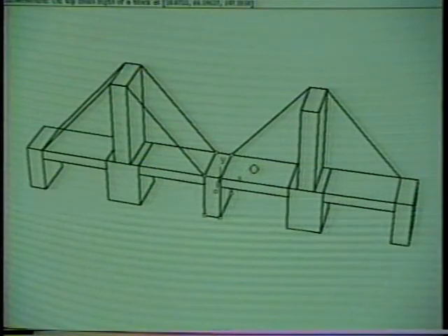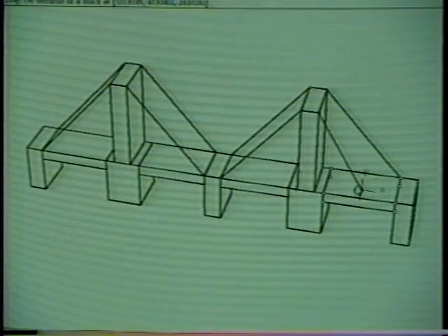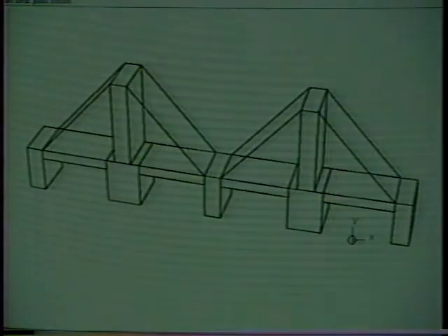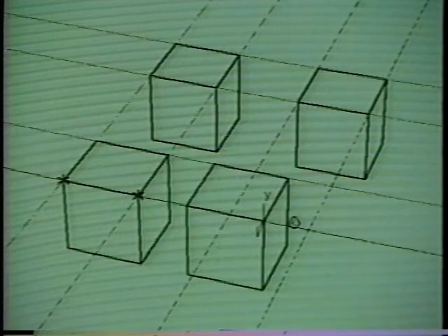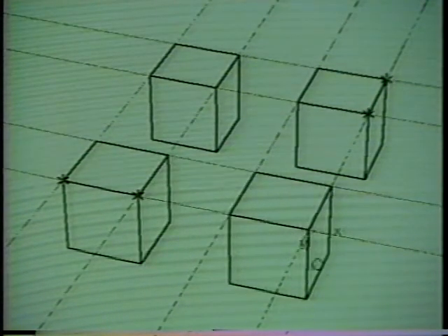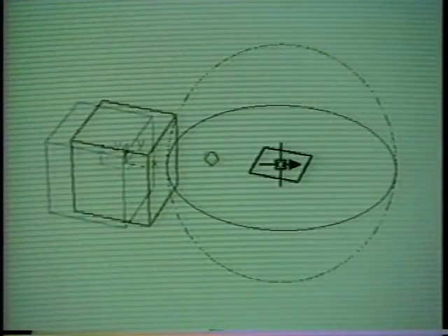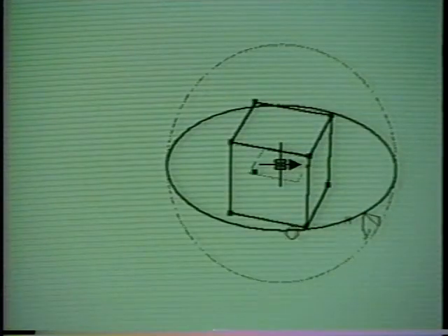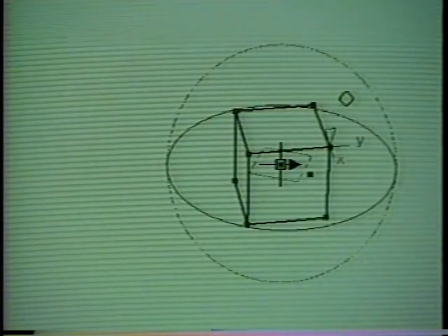In summary, gravity can be used to snap the skitter to faces, edges, and vertices in the scene. Alignment objects provide additional surfaces, curves, and points to which the skitter can be snapped. Transformations, such as translation, rotation, and scaling, all follow the skitter.